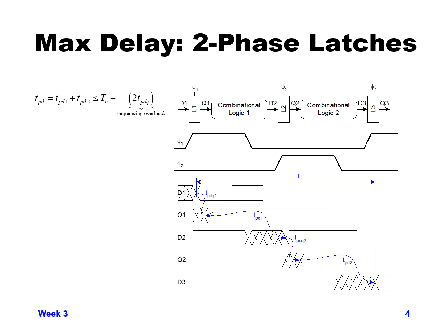And so this is a little bit more of a benefit over doing flop-based design, where we have this really high setup time, which tends to be a little bit higher than propagation delay. The other thing is the propagation delay through the latch could be faster than propagation delay through the flop in some cases, if we use these inverting latches.